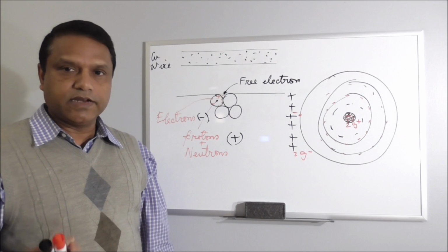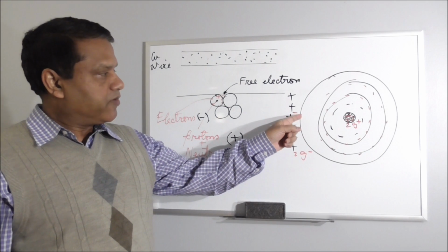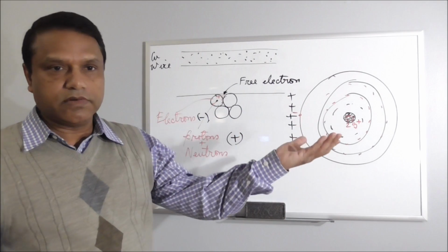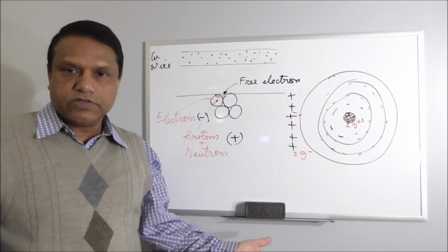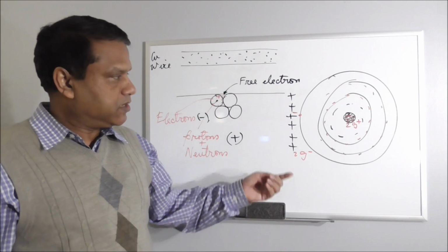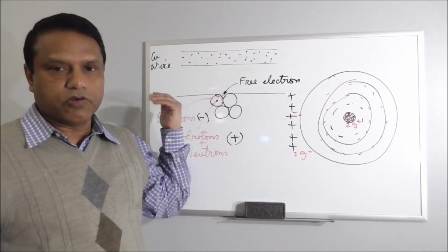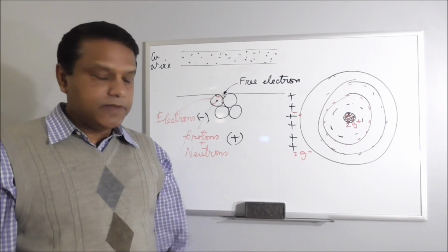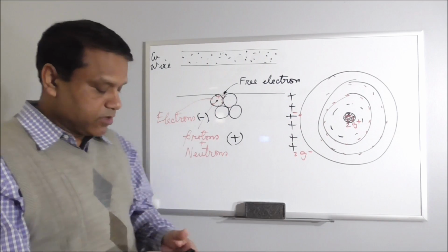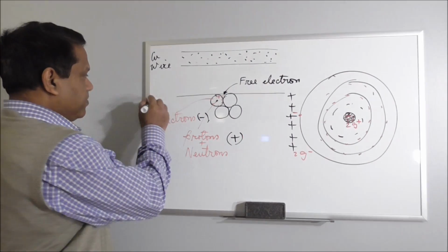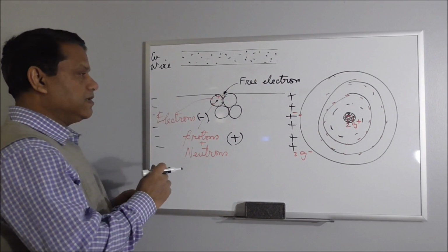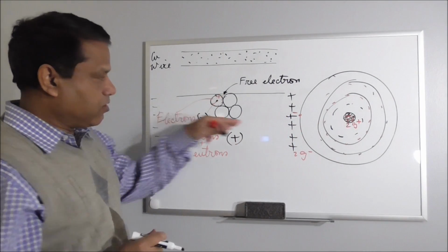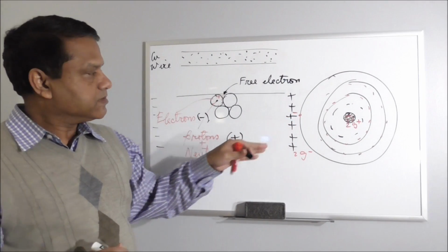For example, temperature, I didn't mention it before. The energy of an electron increases whenever you have temperature increases. Suppose we put it in sun or if the room has high temperature, or normally even at room temperature, it can gain energy to come out of the atom. And those electrons normally do not generate any electricity, but if you apply a voltage, suppose positive on this side and negative on this side, these electrons in general will try to move this way, and that will cause current.